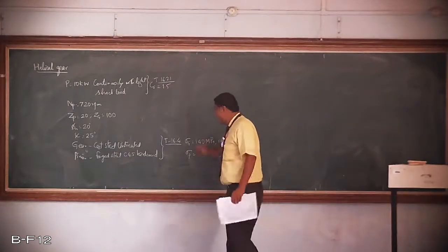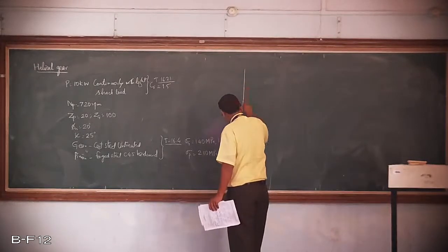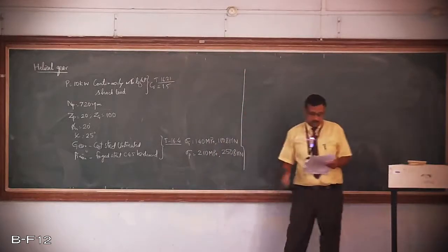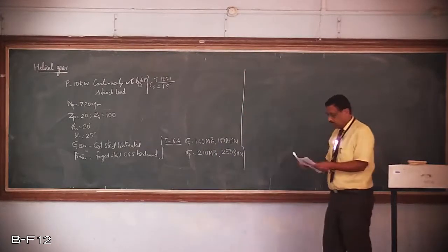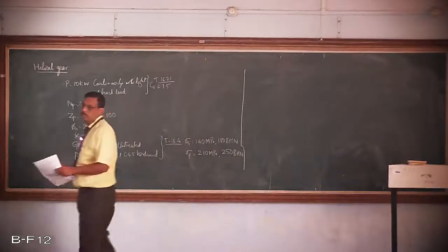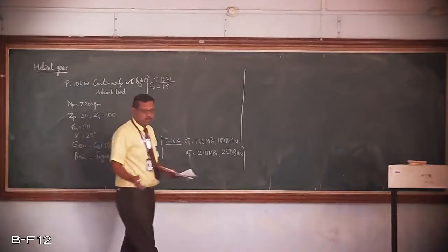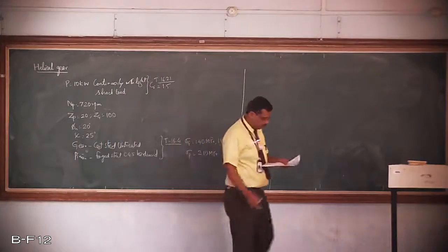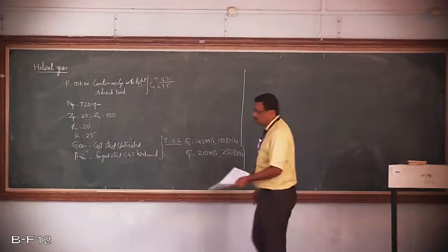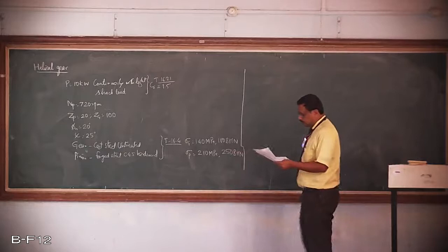Okay, now when the materials are different, the first step for the design of the gears is to check the member which is the weakest member. To decide which is strong and which is weak, we make use of sigma into y, where sigma is the static strength and y is the Lewis form factor. As it is a helical gear, we have to find the virtual number of teeth and not the actual number of teeth. Based on the virtual number of teeth, we need to decide.